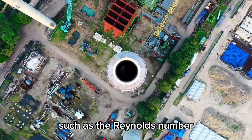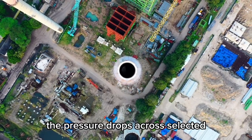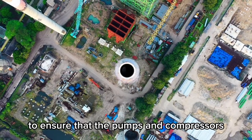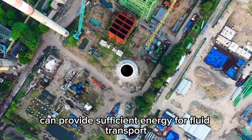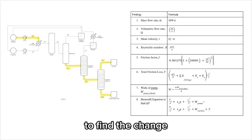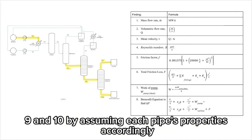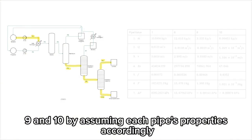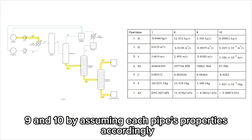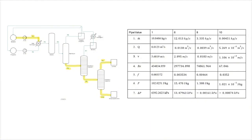Using fluid mechanics principles such as the Reynolds number, friction factor, and Bernoulli's equation, the pressure drops across selected pipelines were calculated to ensure that the pumps and compressors can provide sufficient energy for fluid transport. This is the step-by-step procedure and formula to find the change in pressure for pipe 1, 6, 8, 9, and 10. By assuming each pipe's properties accordingly, this is the simplification of the change in pressure of each pipe.